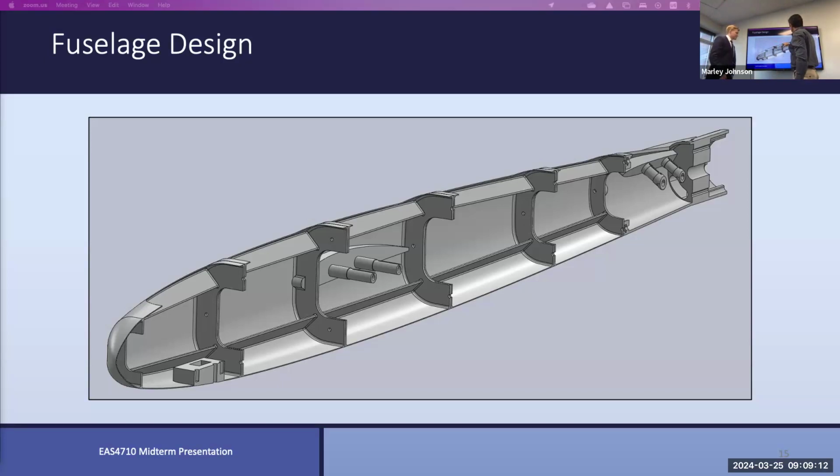Whereas if the fastener is close to the longeron, that's where all of the longitudinal tension force will be, and it'll drive right into the fastener. So out here is inefficient structure, whereas tucked in here is a better load path. From a structures perspective, that's another step.